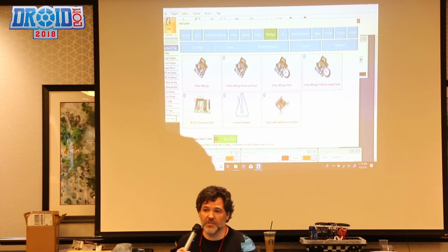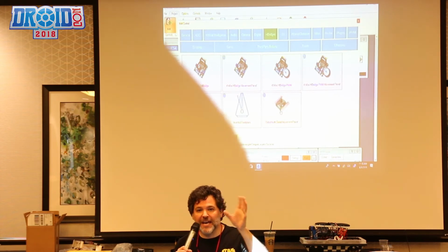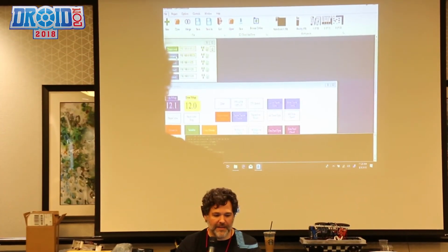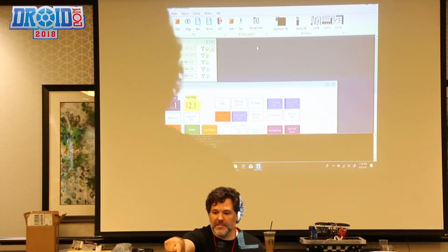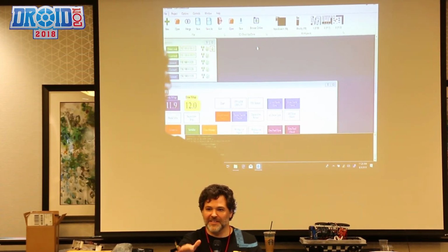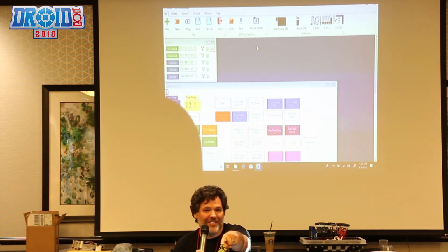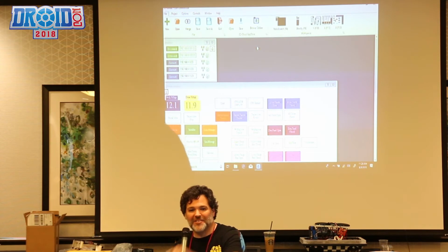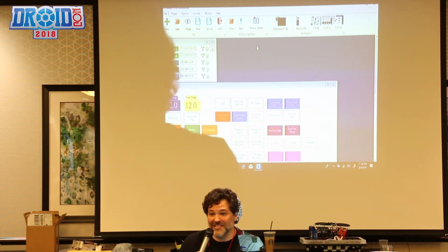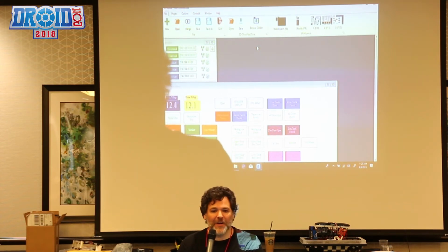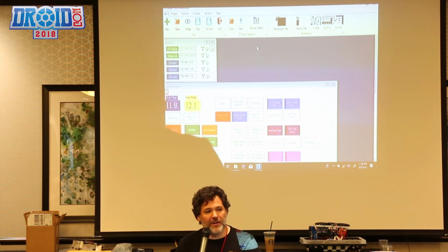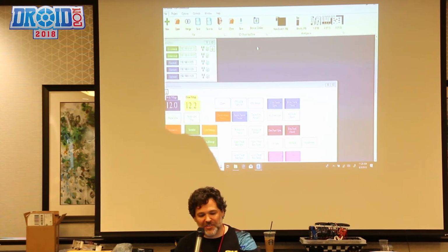Right now, I'm using this Xbox 360 piece, which I have memorized. EZ-B went offline because of the interference, probably because of this thing sitting here, because I'm using a Wi-Fi antenna. Basically, you get a Faraday cage here, which is trapping all your stuff inside, which is why the Surface works awesome when it's inside. It's great inside. So what I'm working on is upgrading his nano router so I can get an external antenna outside of him, because I do need to get the antenna outside eventually. But for the most part, I've been running this since the beginning.